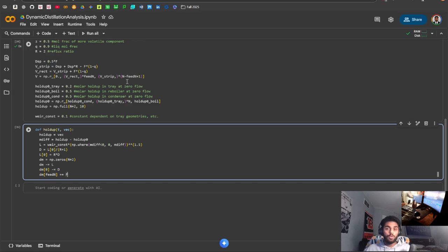So we have some moles of vapor, and that amount of vapor is also leaving our tray. There's going to be some mass diffusion, but the moles of vapor entering our system, the system being a single tray, will equal the moles of vapor leaving that tray. That's the big assumption we are making here: we don't have a dynamic change in our vapor flow rates.